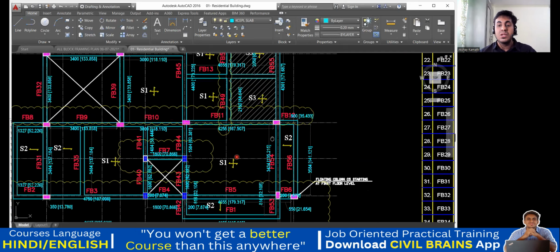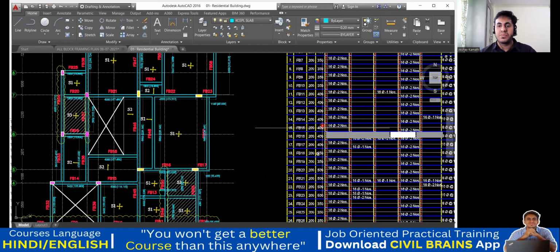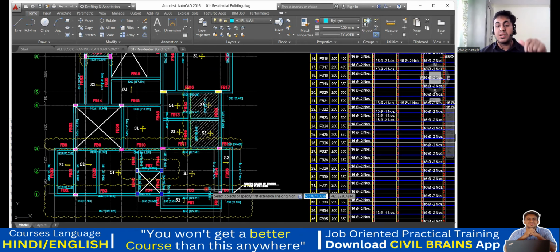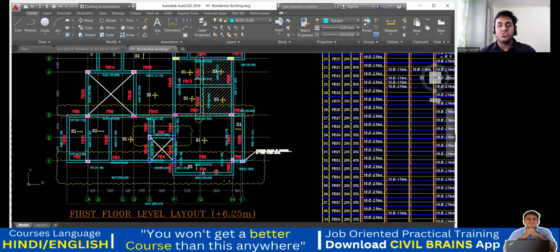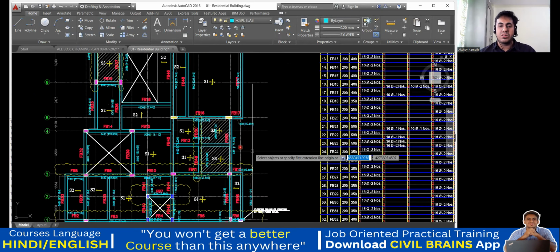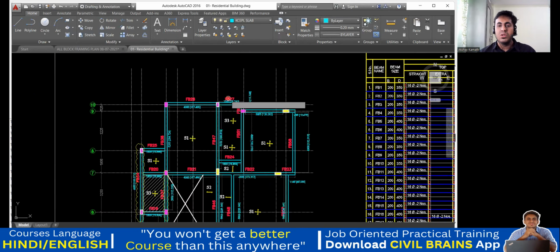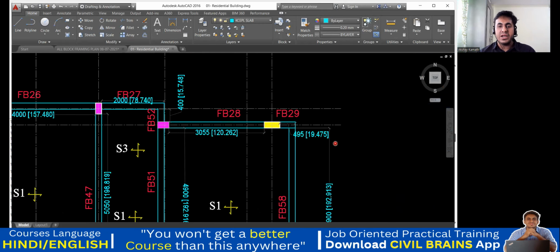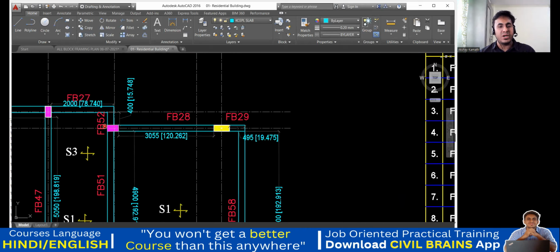Make sure the beams are of the same depth. If beams are of different depth, then you cannot directly multiply the length with the breadth and the depth, because the depth portion will vary. So you can adopt this method, provided the depth is the same. Try to follow this method, which is very simple. Otherwise, if you are finding it difficult, take individual beams. That also you can do.